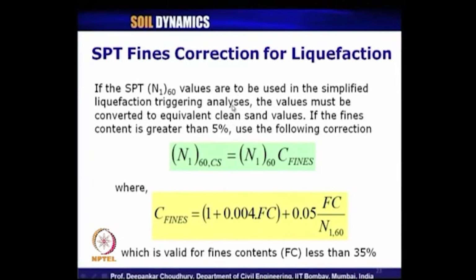So, these are required only when you are going to do the liquefaction analysis. Remember, these corrections are not required for any analysis other than liquefaction. So, these are additional corrections, SPT fines correction for liquefaction. Why is this fines correction required? Let us read the statement.